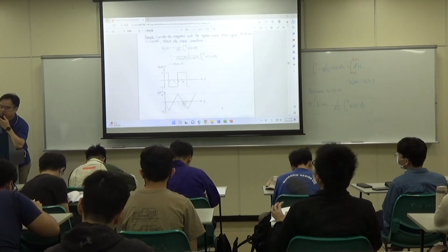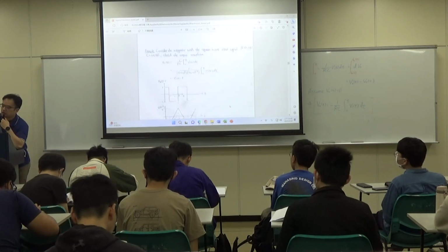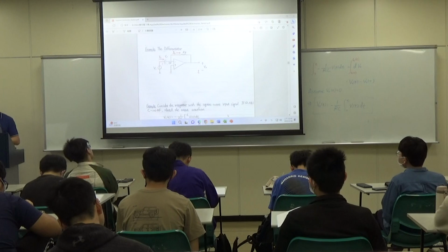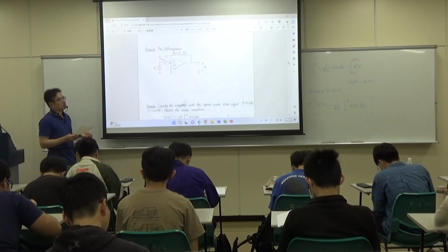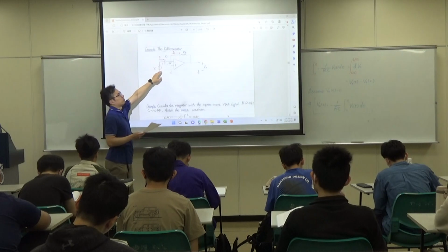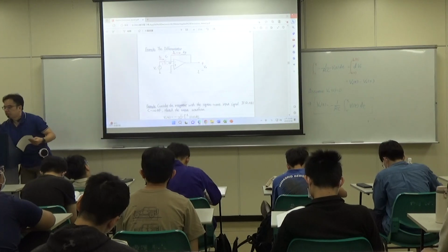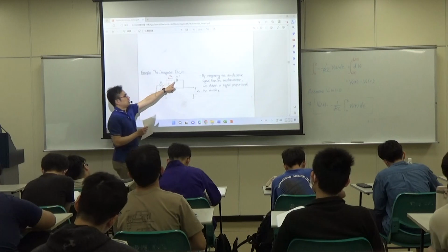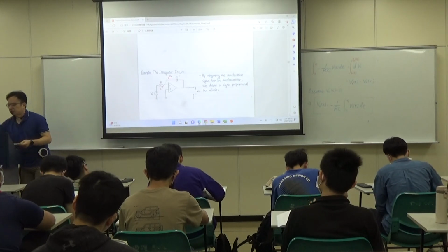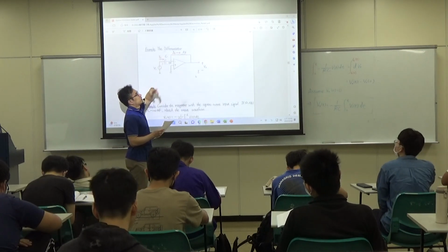Okay, the integrator is to replace the feedback resistance with a capacitor. So we have the integrator, and we also have the differentiator. Remember, we all apply this on the inverting amplifier, right? For the integrator, you just replace the RF in an inverting amplifier with a capacitor. For the differentiator, we also look at the inverting amplifier and replace the input resistance with a capacitor.